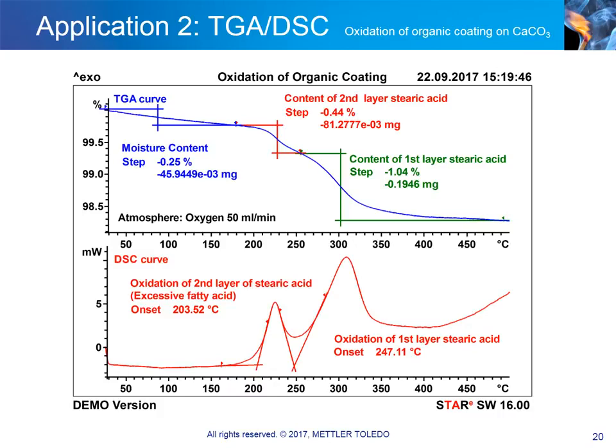With excess stearic acid, additional layers may be formed. A minimum amount of stearic acid is needed to ensure compatibility. With excessive amounts of stearic acid, the mechanical properties are affected and the cost is greater. Thus, the amount of stearic acid on the calcium carbonate particle's surface is crucial from both a technical and an economic standpoint.